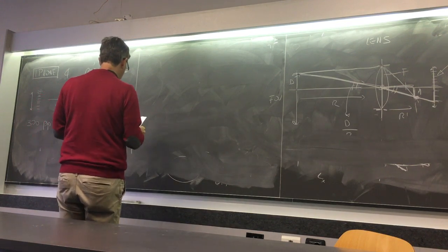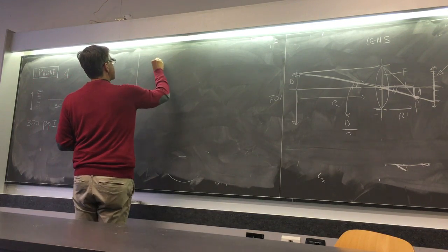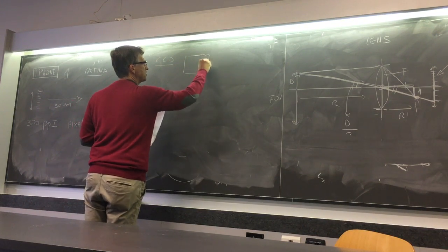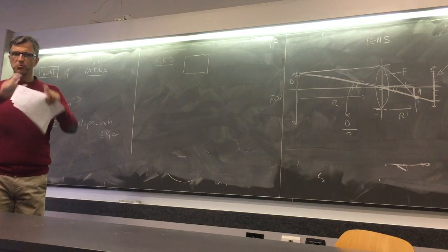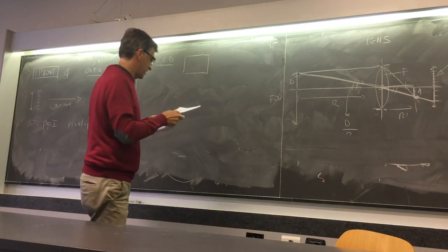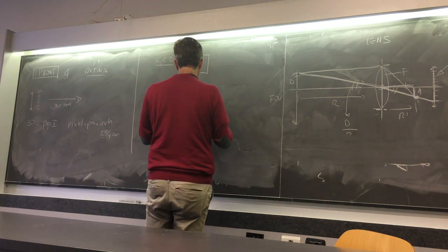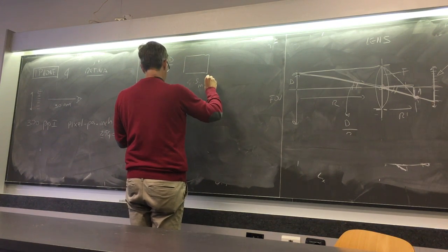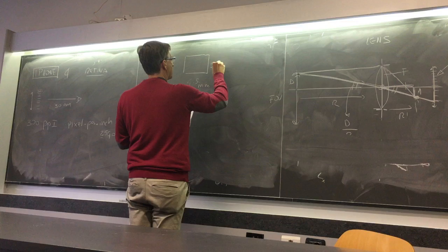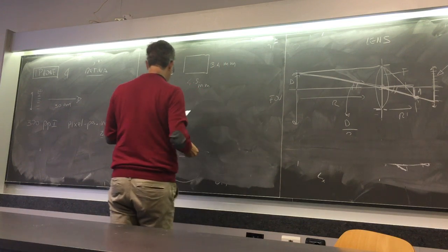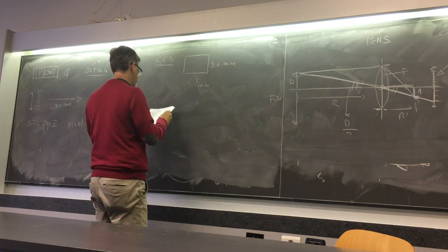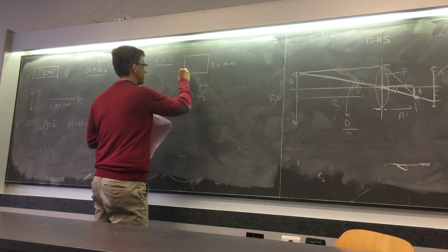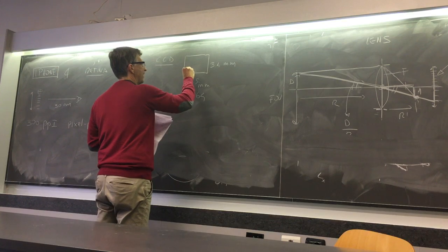So the sensor of the iPhone was using a CCD. A CCD is a matrix. Of course, the image is made this way, so it depends on how you rotate, that was approximately 4.5 millimeters multiplied by 3.4 millimeters. Okay, and the number of pixels on the sides was 3064. This is a number of elements.